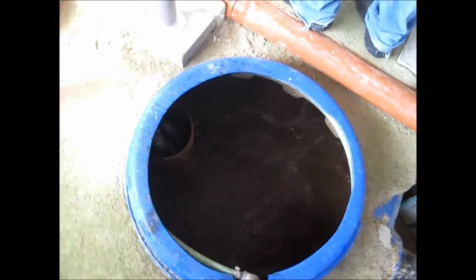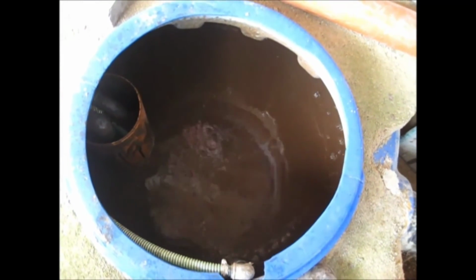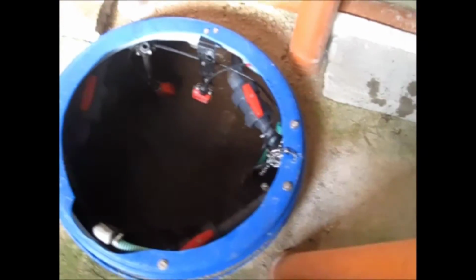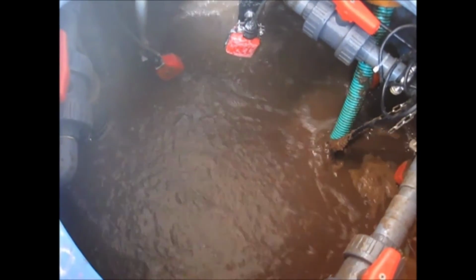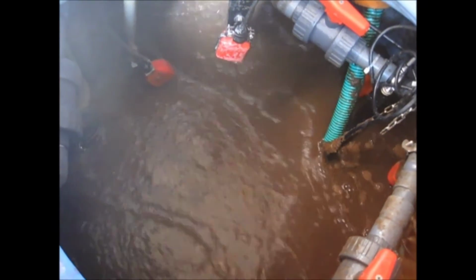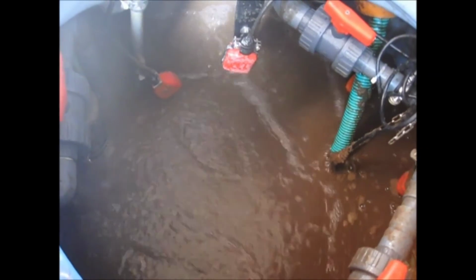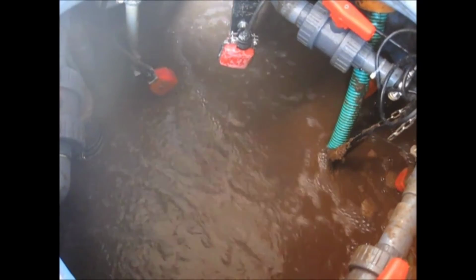After aerating the first reactor for a little bit, this process is stopped as well, and the second reactor is aerated. Here, much more oxygen is given to the water in order to ensure aerobic conditions. After a while, this process stops too.